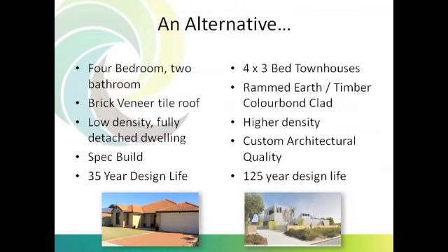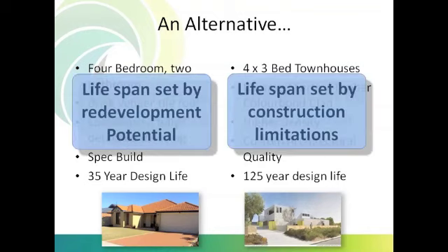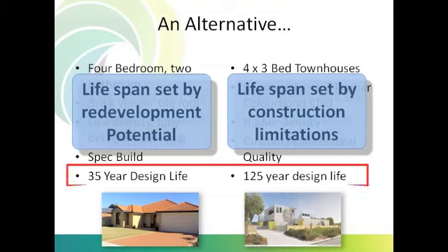Expected lifespan is higher. In this case, it is bound by the durability of the construction. The benchmark, on the other hand, is bound by the redevelopment potential. It is much harder to redevelop buildings with shared walls and also more expensive whilst ever there are detached houses in the surrounding streets, which make easier targets for purchase. The result is a 3-fold increase in expected lifespan.